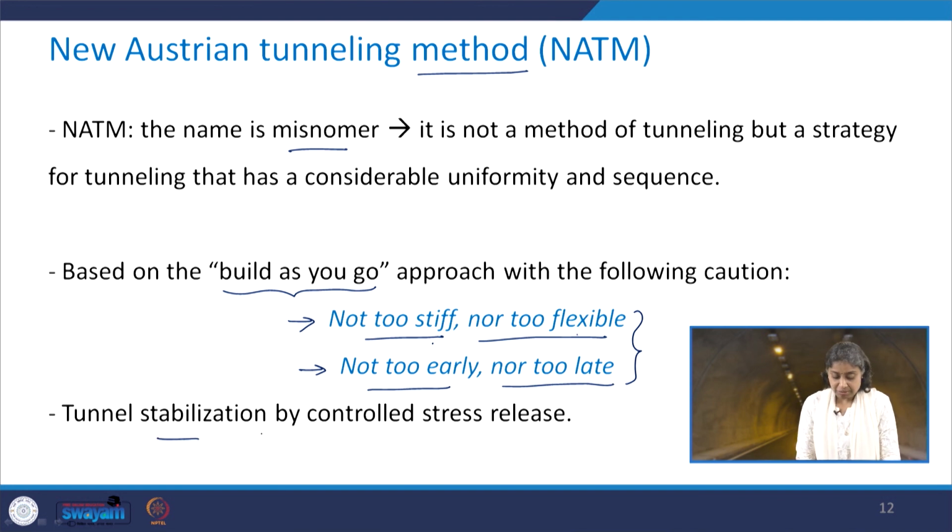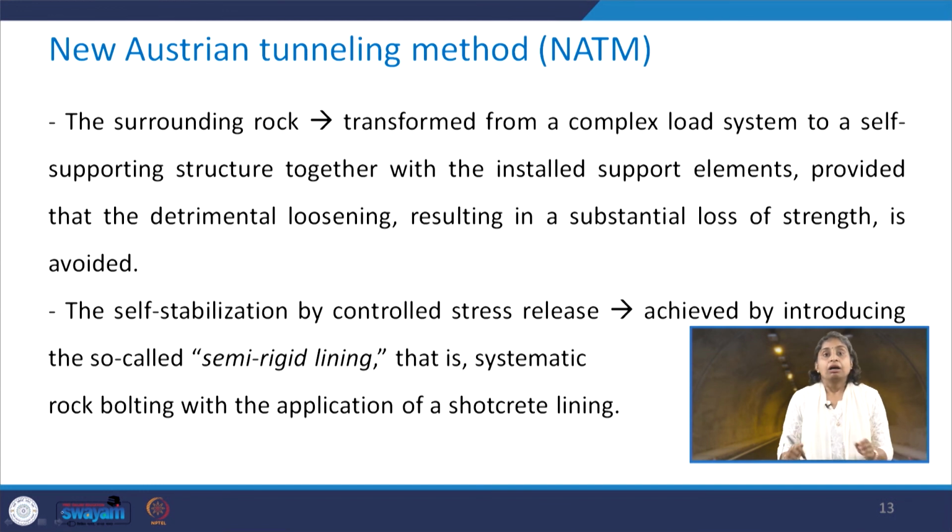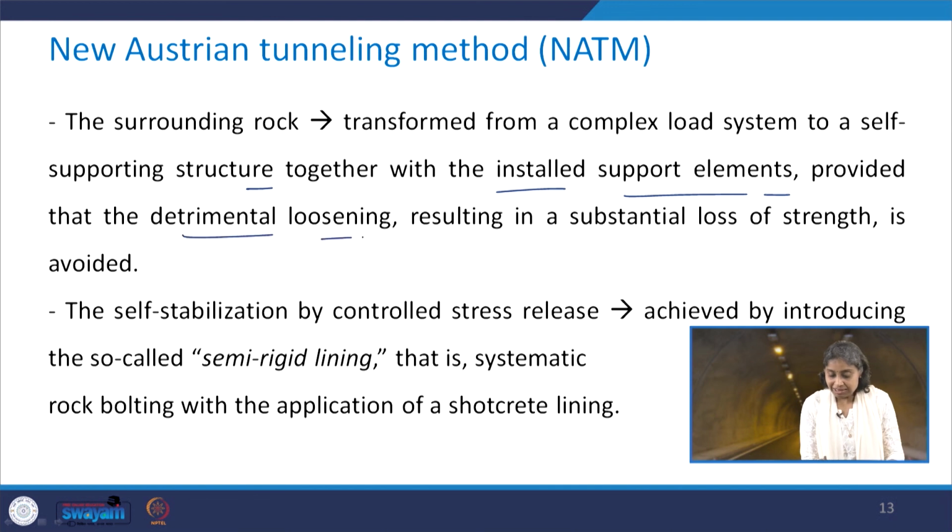Then the tunnel stabilization should be done by controlled stress release. The main aspect related to NATM is that the surrounding rock is transformed from a complex load system to a self-supporting structure together with the installed support elements, provided that the detrimental loosening resulting in a substantial loss of strength is avoided.